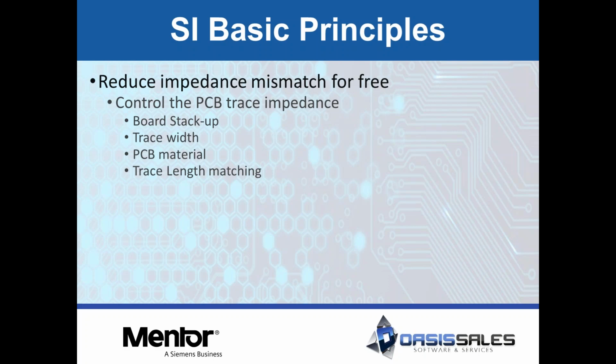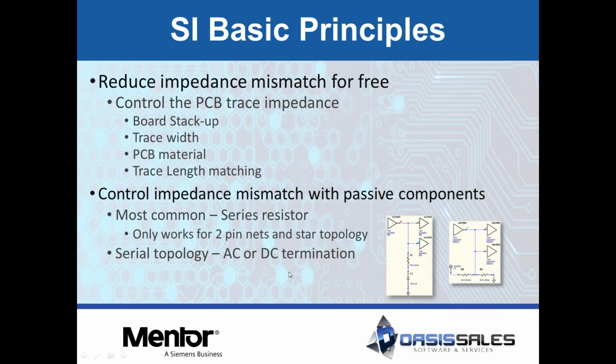So like we always come back to the clock network. If you're using one chip to distribute a clock to multiple devices, you may want to put a series terminator in and then do a star pattern configuration from that resistor to each of those devices, and make sure you length match the nets within a certain distance of each other to reduce the reflection time delay differences, and make the signal as clean as possible to those devices. So playing with trace length, it can be a big help. Something not a lot of people think about.